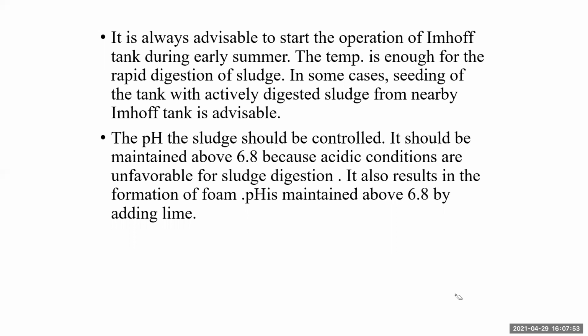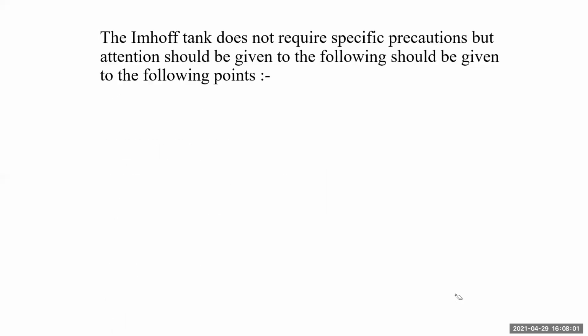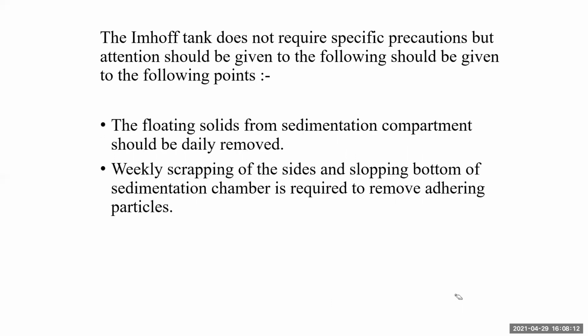By adding lime, we have to maintain the pH above 6.8 so that sludge digestion takes place very efficiently. Okay, the Imhoff tank actually does not require much attention or precaution, but we have to follow certain things. The first thing is the solids that float on the top of the sedimentation compartment. The upper chamber is called the sedimentation chamber.